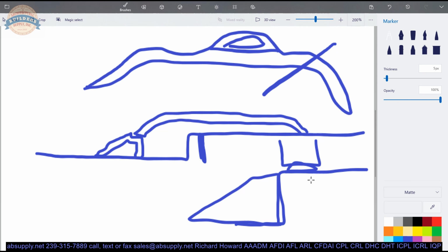Thresholds that have been ripped down like that. What the client elects to do, or better said, if the client were to get approval from the authority having jurisdiction, then you would be in good shape. But my suggestion is everything, the door, the threshold, needs to all be fire rated. If you put some ramp transition in front because it's not underneath the door, I don't think you'll have a problem there. So that's what an elevator is for.